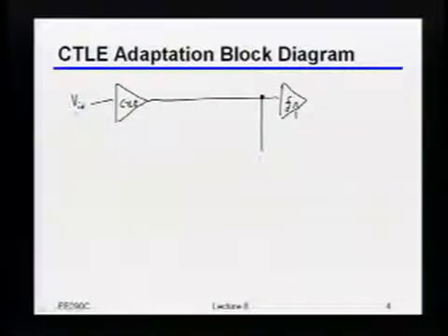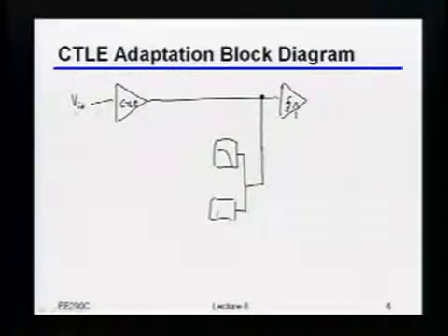Can I just put a filter? Yeah. Do I need one filter? Two. Two filters, right? So I basically do one low-pass filter and one high-pass filter. If I've done this right, the cutoff frequencies of both of those filters should be the same. There should just be some half-point frequency. Now once I've done that, how do I decide which one has more energy? Or how do I compare the energies?